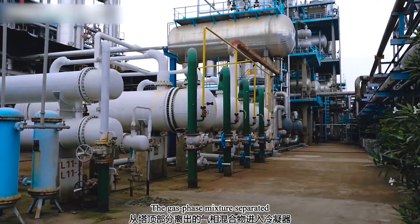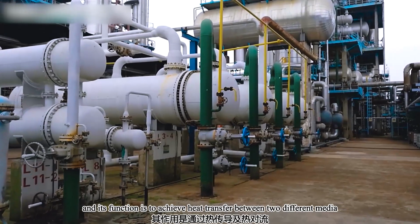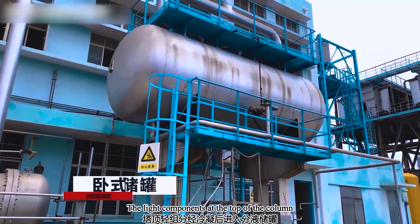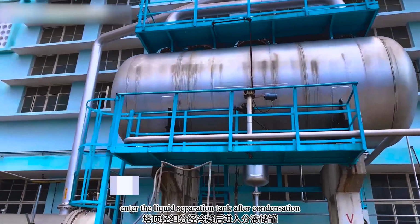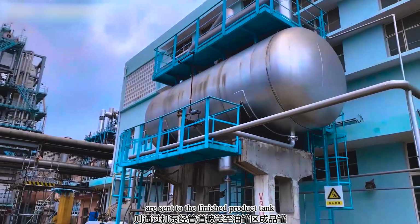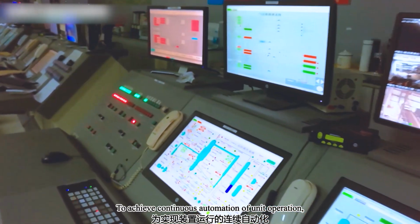The gas phase mixture separated from the top of the column enters the condenser. The condenser is a type of heat exchanger, and its function is to achieve heat transfer between two different media through heat conduction and heat convection. The light components at the top of the column enter the liquid separation storage tank after condensation to achieve liquid-liquid separation and liquid-gas separation. The heavy components in the column are sent to the finished product tank in the oil tank farm through pumps and pipelines to achieve continuous automation of unit operation.